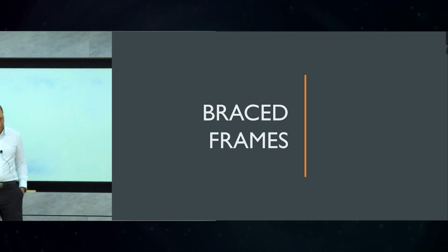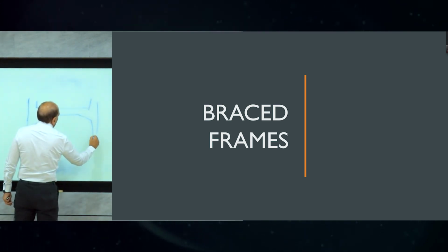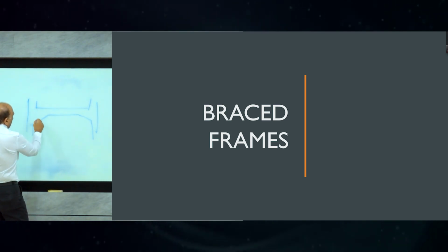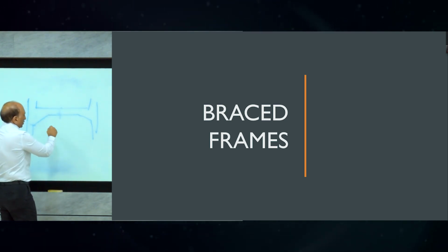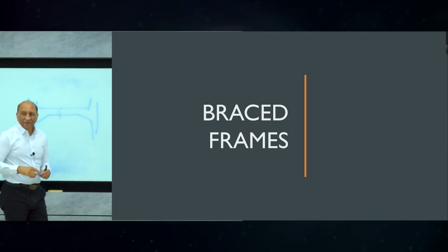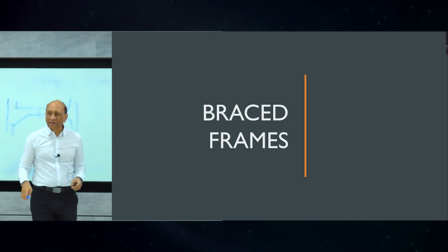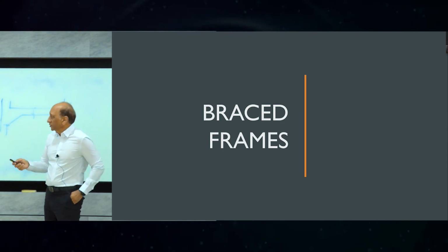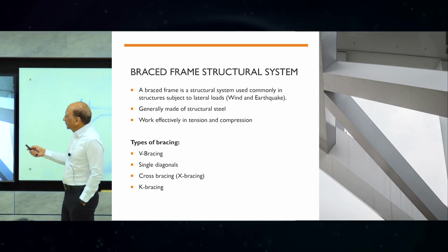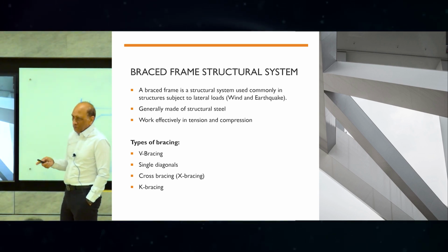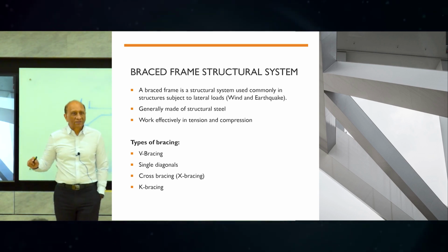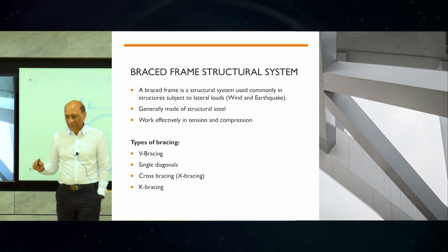Arched beams are okay. You make the beam like this: you increase the size of the beam close to the joint and then reduce the height in the middle, so people can still use it, but you increase the haunch at the joint and it increases the stiffness. So this is another option some people can use, haunched beams. Okay, a braced frame, as you have seen, bracing is very useful, very helpful, because it immediately locks the shear deformation of the entire frame.